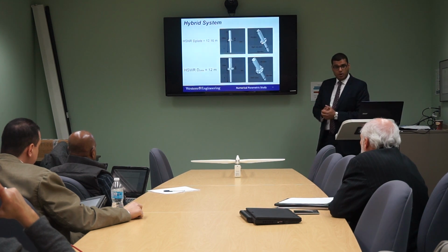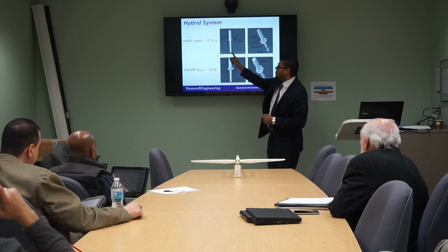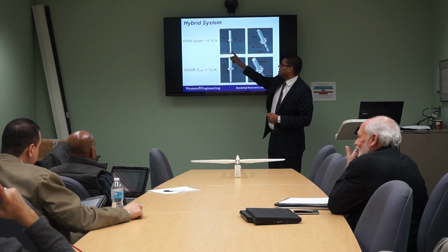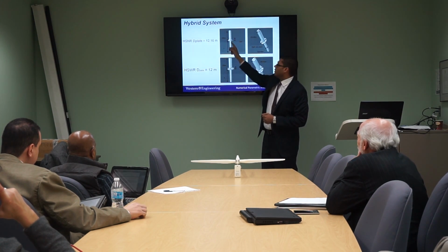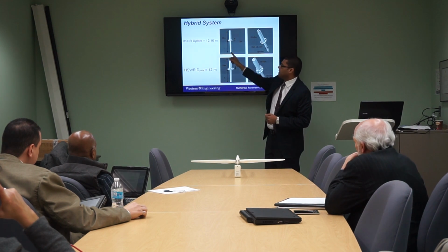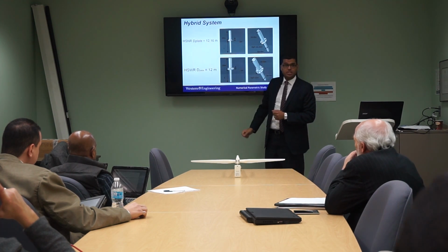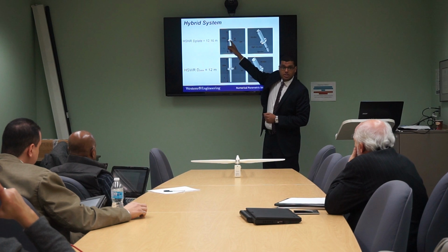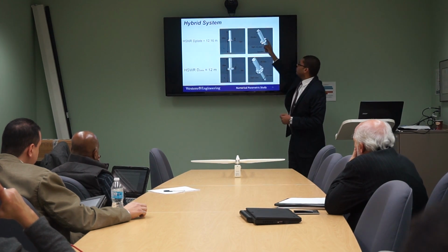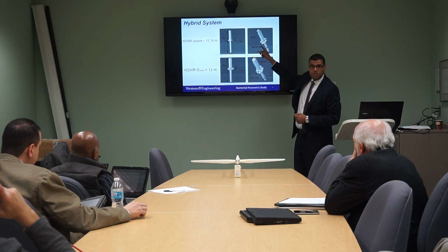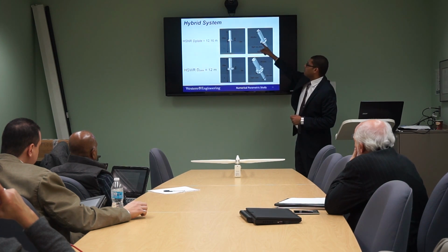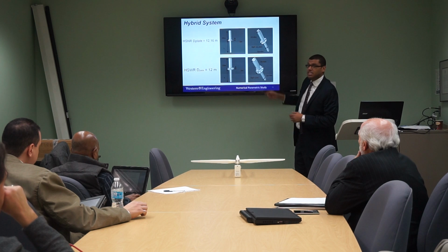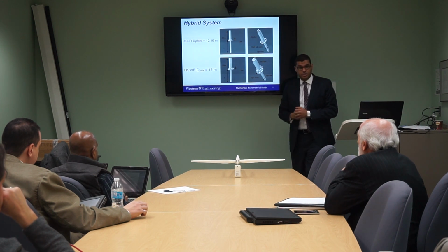And then our hybrid foundation system, which will be a smaller pile, a monosteel pile with diameter 4 meter, and the upper part with diameter 6 meter, with water depth 20 meter, with different lengths. And you can see here we also changed the blade diameter from 12 to 16 meter. And as we said, the blade sometimes will be without ribs, and sometimes with ribs, to see the effect of adding or removing the ribs.